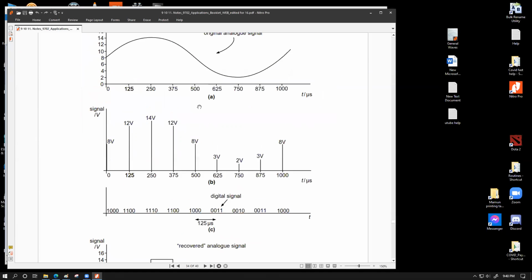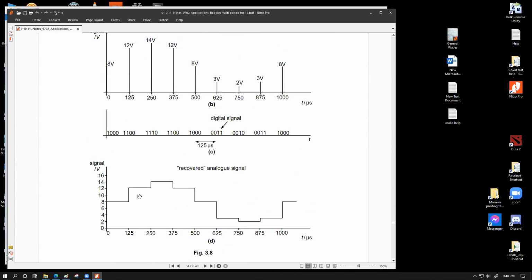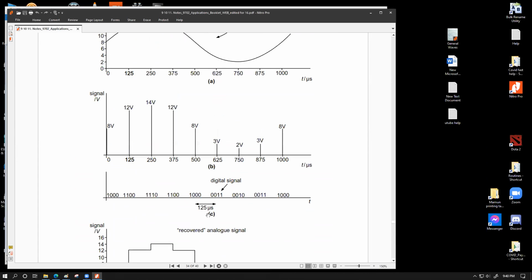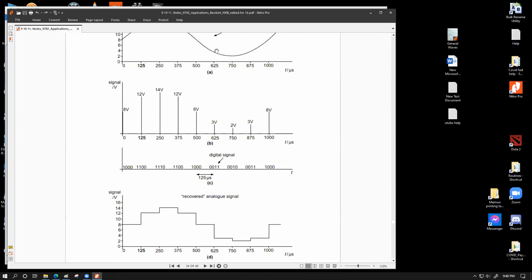So it is not as smooth as this one, but we can increase the smoothness of this graph, or decrease its graininess, by doing some specific things. We're going to see those things in the next class. But this is a very basic conversion process for how digital conversion is done. We have the analog signal, we chop it with the sampling frequency, we convert the sampling voltages to binary, we transmit this binary over a communication channel. On the receiving end, we convert those binaries into decimals, which is not shown over here because it would be just the other figure over here. Then those values are used to recreate the original analog signal, which somewhat looks like the original signal.